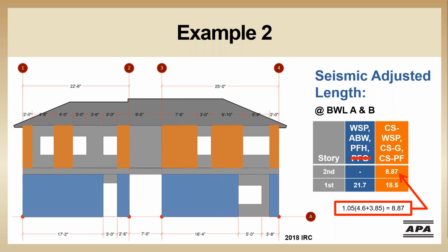Now, also remember this line is longer than 50 feet, so we split up the line length to find our required braced wall panel length in the table. Now on this side of the building, our exterior wall jogs at braced wall line 3. And so that's where I've decided to split it. This gave us a braced wall line length of 29 foot 8 inches, which I'm just going to call 30 feet to the right, and 25 feet to the left.